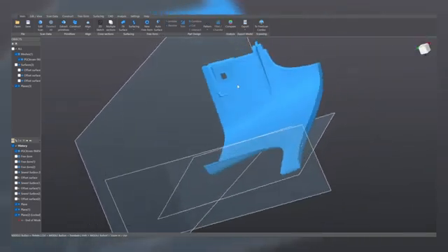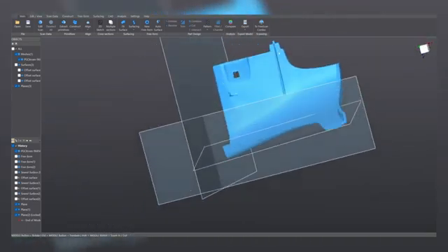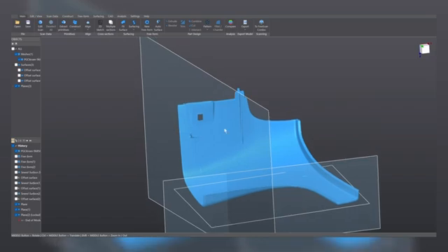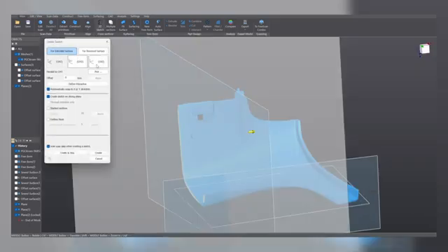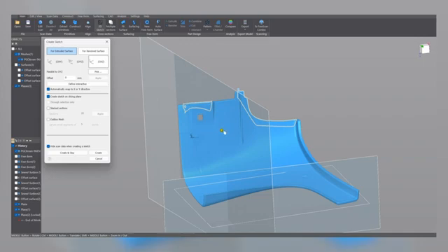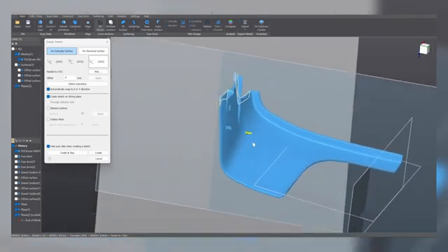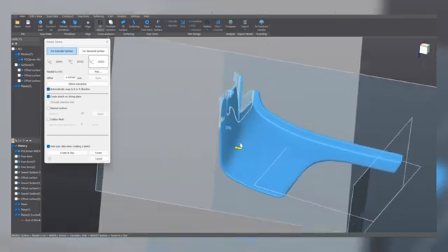Cool. Now, for this geometry here, the way to approach it is by extruding a sketch, an open sketch, to obtain a surface. So let's do it. Click on 2D sketch, select the proper orientation, and the first thing that we observe is that when moving this plane, we are not able to slice on the position that would work well for us to extract this information, right?